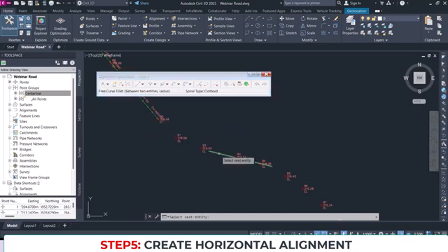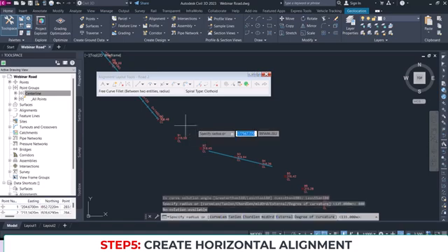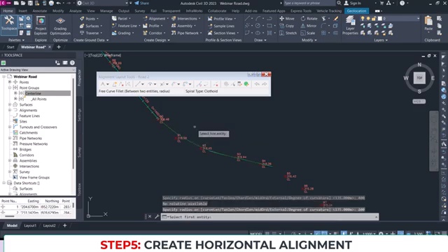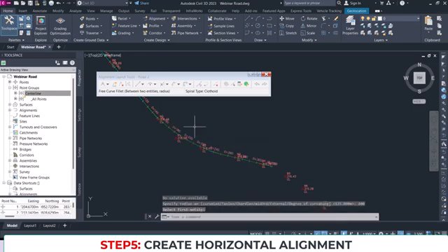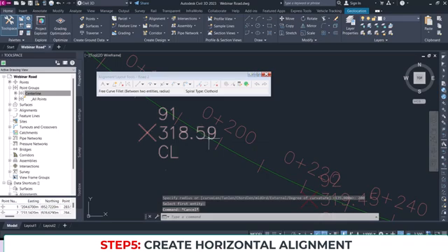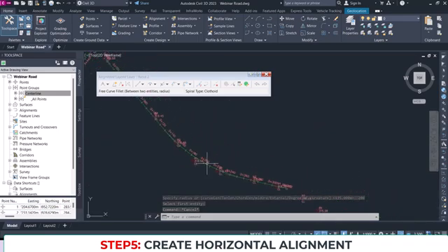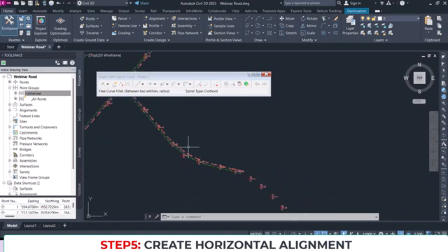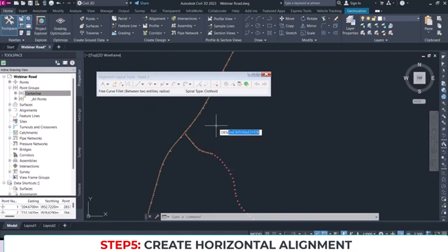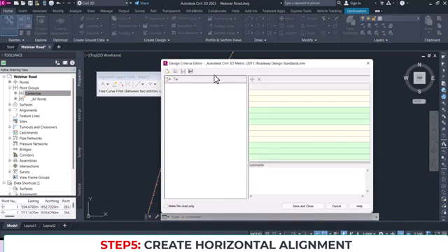So then I will have to put in a fillet curve, and then add a radius. It's less than 180, and then we can use a radius of, let's say, 400 is too much, so let's say 200. That works. But is it within the design code? Yes, because we don't have an error. How do we know what is the minimum radius for a road of 60 kilometers per hour? You can find that in your design criteria editor. You can just quickly check on that.